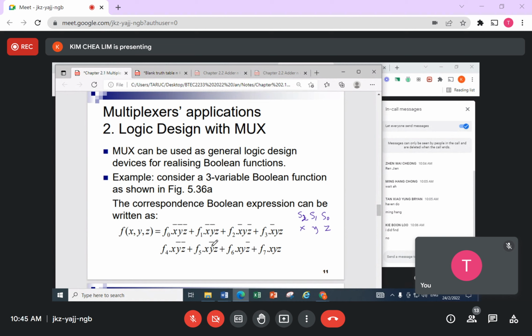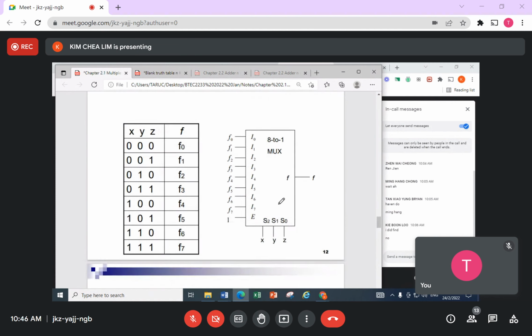So this is the general equation, or the Boolean expression before we do any simplifications, for a 3-input selector line of a multiplexer. If I want to do logic design with these multiplexers, let's start off with something very simple. These are my 3 input variables. So 2 to the power of 3, recall, for a truth table I must have 8 combinations.